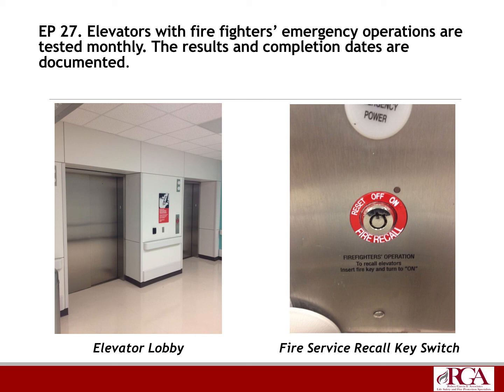So you go into the elevator car, you put the key into that car, and then you take independent control of it. You move it to the second floor, third floor, check the hold open and the close buttons, make sure those are working properly. That's a monthly check. In addition, you want to check the emergency call button, and you also want to check the local alarm or bell, the local audible alarm. You want to check those two.